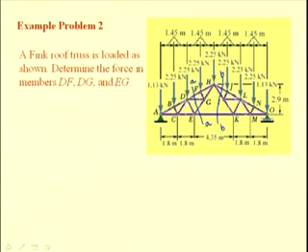Since this section passes through only 3 members, it is possible to determine all the 3 forces. Once we have determined this force EK, we can go back to the previous section, and now we will have only 3 unknowns, that is DF, DG and EG, and the problem is solvable.